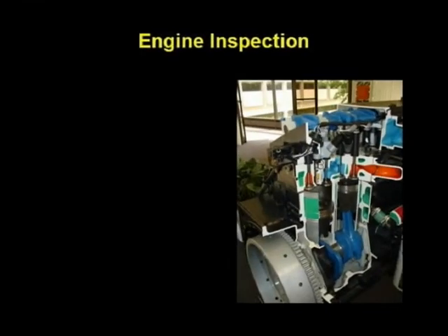a non-destructive evaluation. Just about every component on a Cummins diesel engine either is being or has been inspected at one time. The block and head castings can have problems with porosity, cracks, core shift, type of iron, and physical properties. Magnetic particle inspection is used for crack detection. Ultrasonic inspection is used for wall thickness measurements, detection of porosity, and determination of type of iron. Eddy current inspection is used to check hardness and to find chaplets too close to the ID of cylinders.